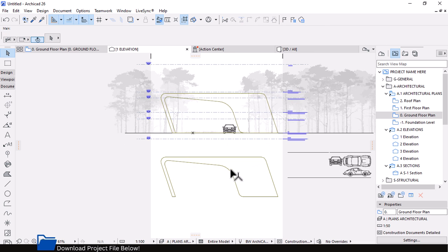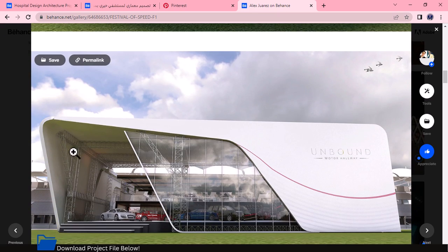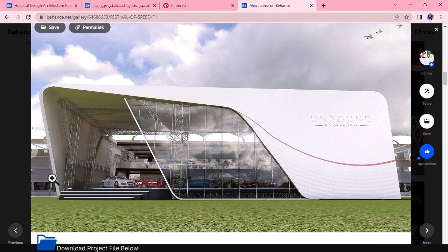So let's go to the design tool palette. We're going to use a morph tool to carve this. You can use different types of tools. Even a complex profile can still do the job, but for this type of exercise I would use the morph tool. The reason being, because we don't have a smooth straight curve. As you can see, I said here it's slanting as well.